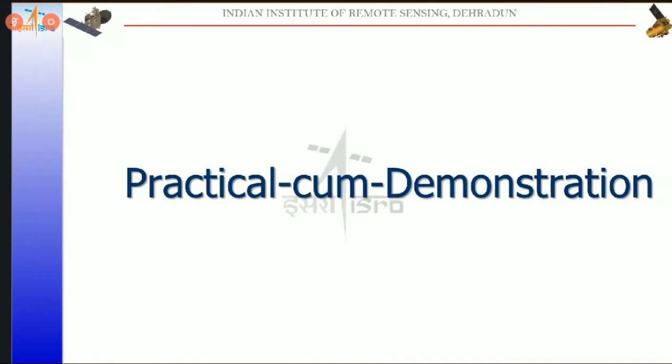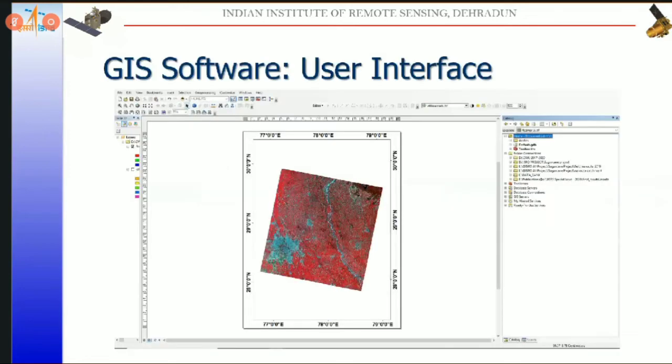So very first, I would like to tell you about the GIS interface. A number of GIS software are available nowadays in the market. Some are free of cost and some are paid. But you can use any kind of software and their plugins, along with freely available satellite data sets, and generate your results easily in the particular GIS interface. So very first, I would like to share the complete steps, how you proceed one by one when you generate the crop evapotranspiration result ultimately.